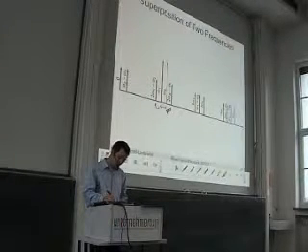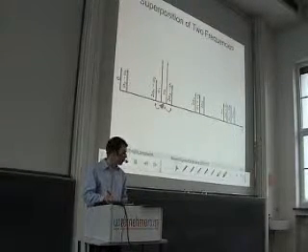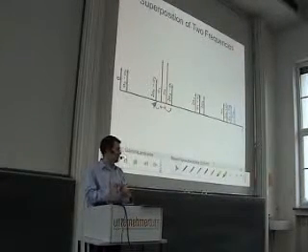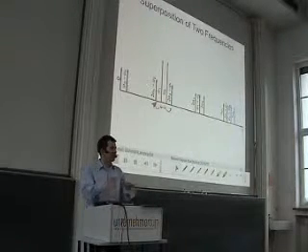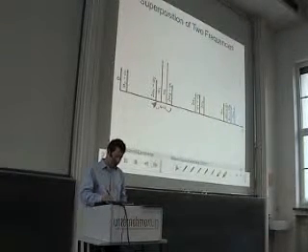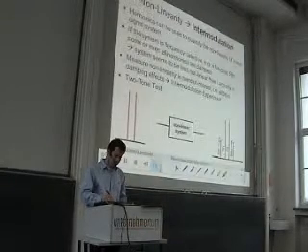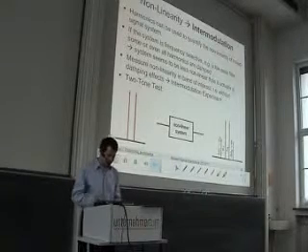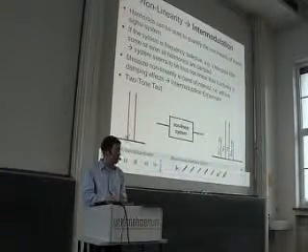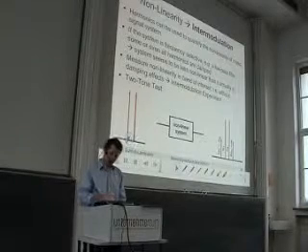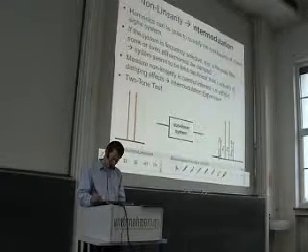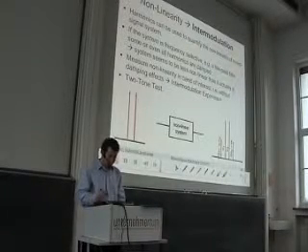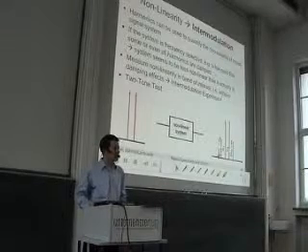So the point is we have to take a frequency difference that is very small, then these two components are nearby, and the frequency selectivity can be neglected. And this is what people describe in the so-called intermodulation experiment. They put two tones into the system, and they use these third order intermodulation terms to analyze the nonlinearity.